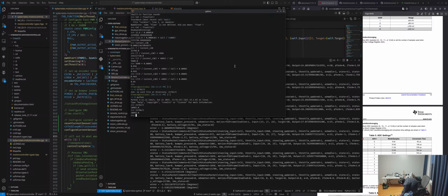Oh yeah, 10.92 volts. Okay, actually it's reading perfectly correctly. That's good. That's real good. Okay, nice. And there's going to be a tiny little loss over the shunt. 10.93 to 10.89, that's 0.04. It's 40 millivolts. I don't care, this is 40 millivolts off.